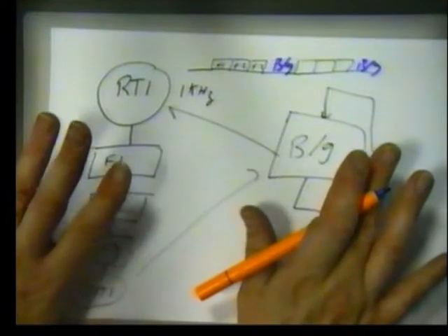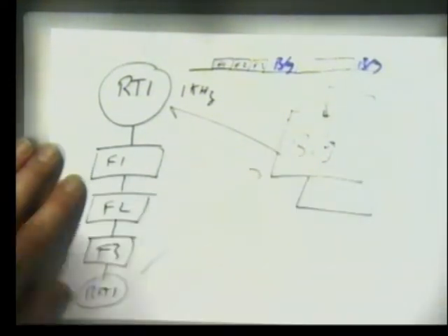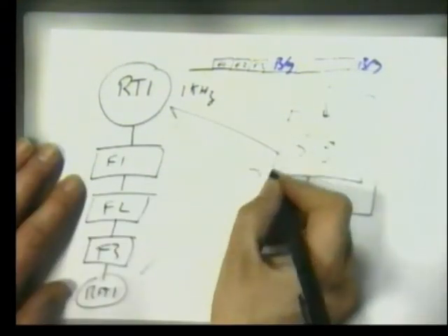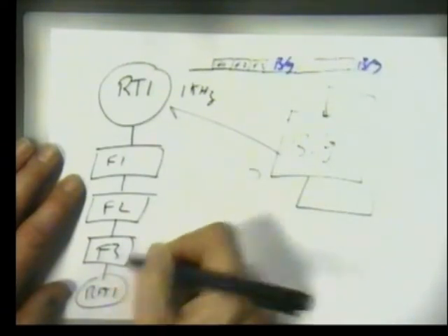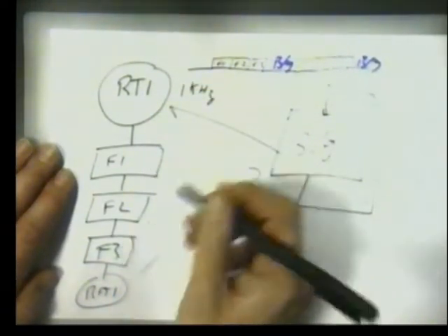So we've moved on now from something really trivial, very quickly, 3 functions, do 1, do 2, do 3. We've very easily moved on with a single interrupt to create a multitasking environment. We have here a background routine. It runs forever, but it is paused, it is suspended to run the fast real-time routines, function 1, function 2, function 3.